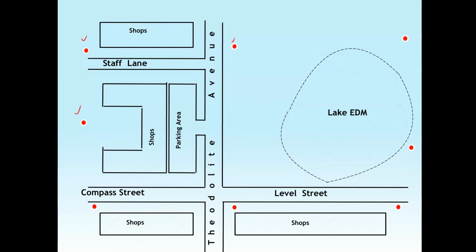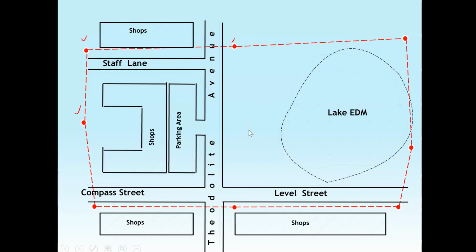So once those points are in the ground, the next step is to find or to determine the coordinates of these points. Then you will simply run a traverse through it, to all the points, measure bearing and distances, do your calculations, and you get all the coordinates of the points.